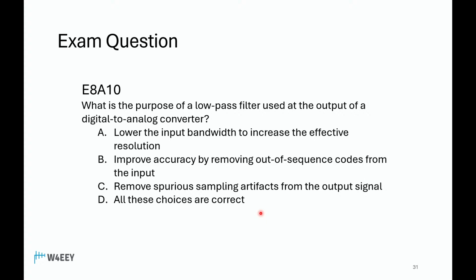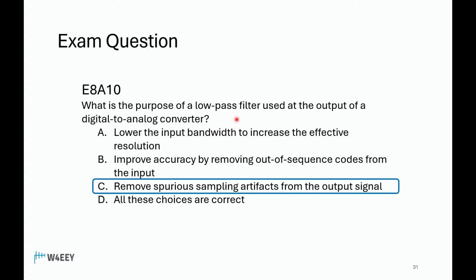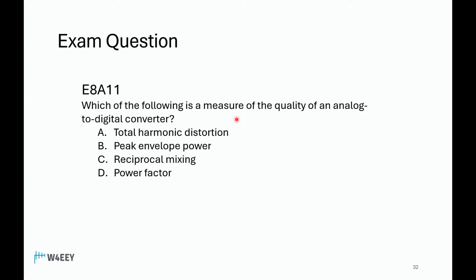What is the purpose of a low-pass filter used at the output of an analog to digital converter? Digital to analog. Yeah, that's even better. What is the purpose of a low-pass filter used at the output of a digital to analog converter? Thank you, Gary. Charlie. Charlie, remove the spurious sampling artifacts from the output signal. Smooth out those stair steps.